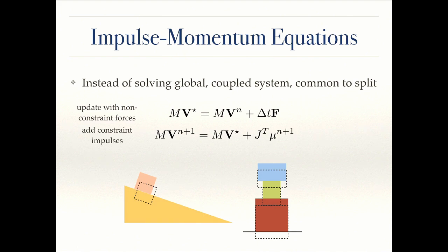After the time integration, my objects are now violating the constraints. Let's say I just had gravity here. I'm illustrating this with positions, but this is just integration on the velocity. So it's really the velocity right now that's violating the constraint and not the position. But the velocity is telling me that if I add gravity, I should go into this triangle, which I know will violate the constraint. So now I want to correct this. If I solve for my impulses globally, I can correct everything all at once, and my state will go back to being like this.